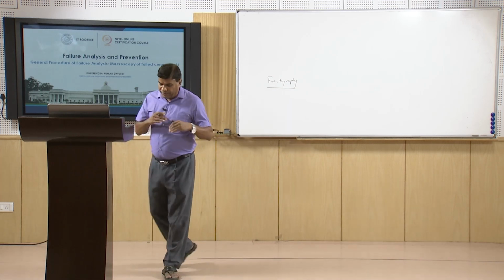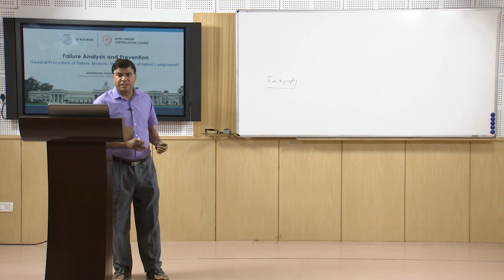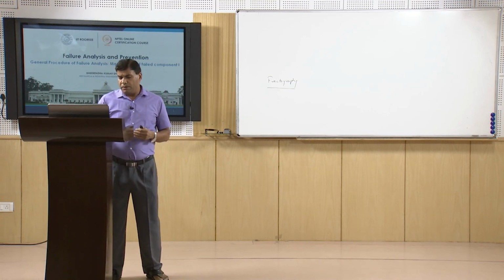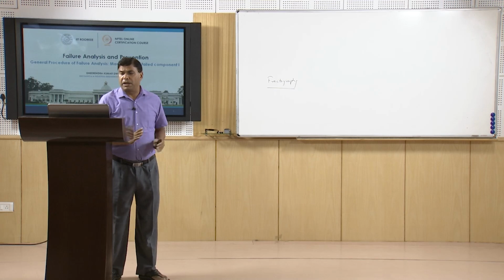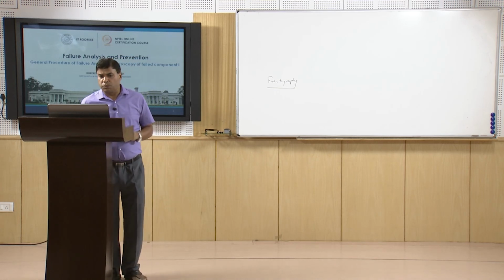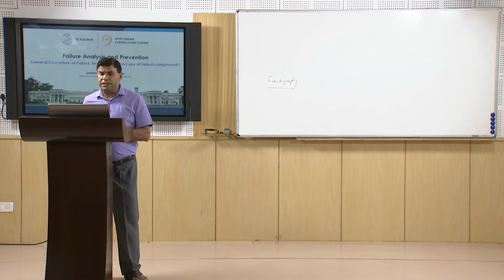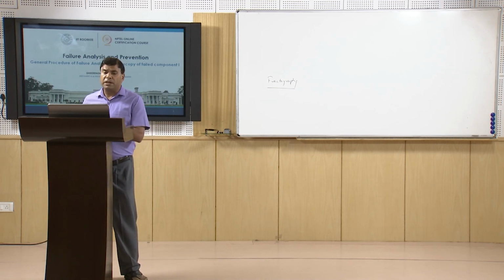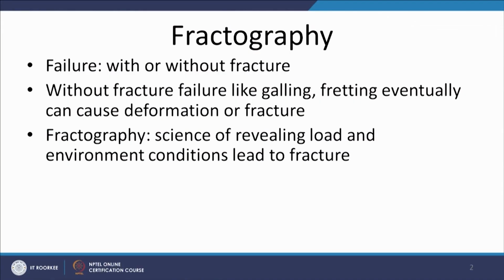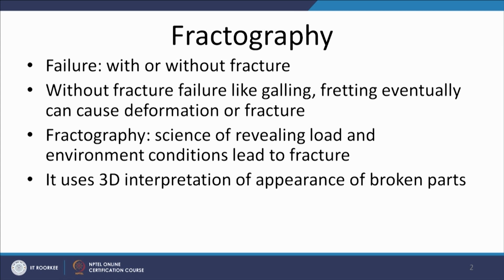If the fracture failures are to be investigated, then we have a special branch of engineering or science wherein investigations are carried out primarily to see under what loading conditions and under what environmental conditions the failure has taken place. Basically, fractography is the science of revealing the load and environmental conditions which have led to the fracture of the component.